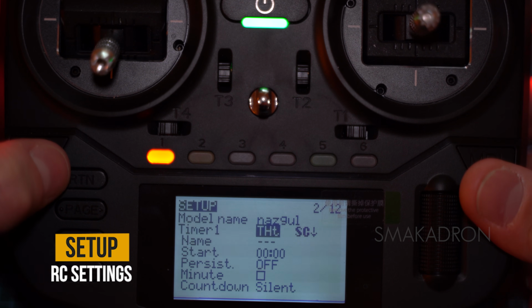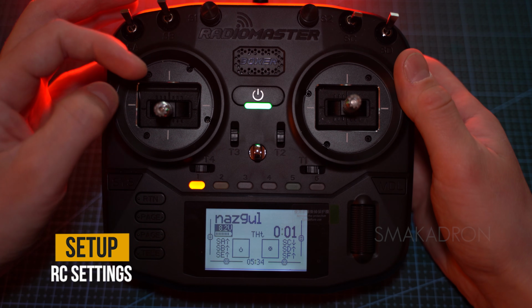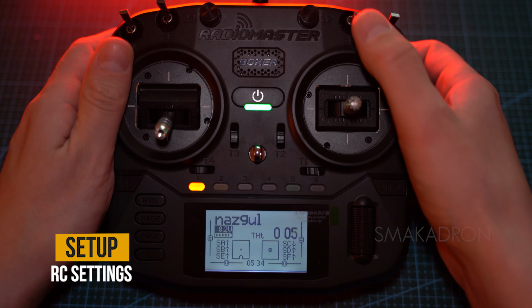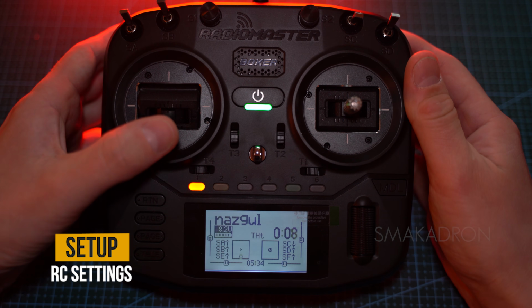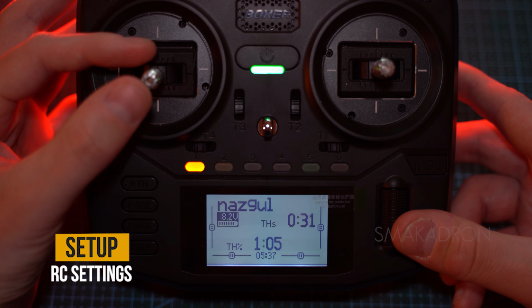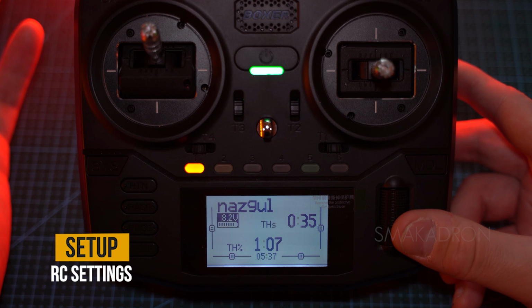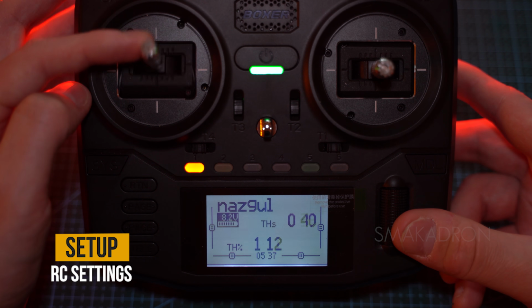Throttle start. The timer starts if the value of the source selected for throttle control is greater than the minimum, for example, when raising the throttle stick and activating the selected switch. After starting, the timer will no longer react to this source and will continue to count until the selected switch is deactivated. Out of the 3 timers, I managed to set up 2, one for the total flight time and the second for the amount of time I was flying the drone with more than 50% throttle. The third timer doesn't fit in the window.